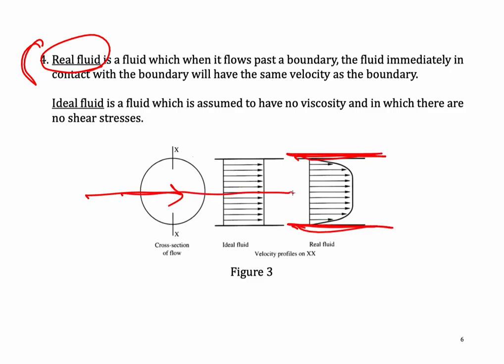When fluid flows inside a pipe like this one, one phenomenon occurs. We learned this in viscosity. We call it the no slip condition. The no slip condition means that the molecules will stick very hard on this surface, and then the velocity here will equal 0. The next molecule will travel slower like this, but the next molecule will travel a little bit faster, and so on and so forth. And then it creates a velocity distribution like this one.